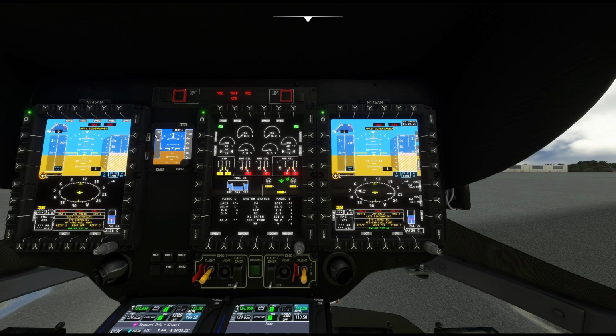All right, and then this is your IESI, your Integrated Electronic Standby Instrument. This performs most of the functions of this right up here. So obviously it has no collective lever position, no AFCS tape, no timer, no decision height, but your main ones are shown over here so that you're able to get an altitude, an airspeed, and an aircraft attitude, and it has a separate barometric.